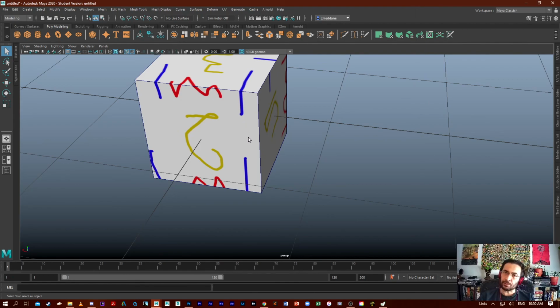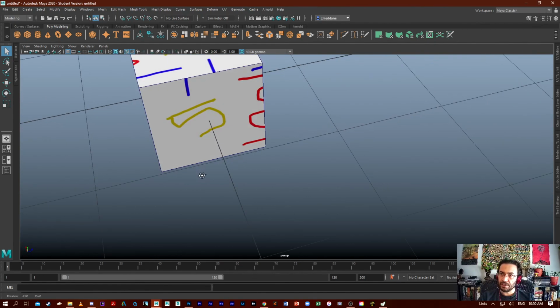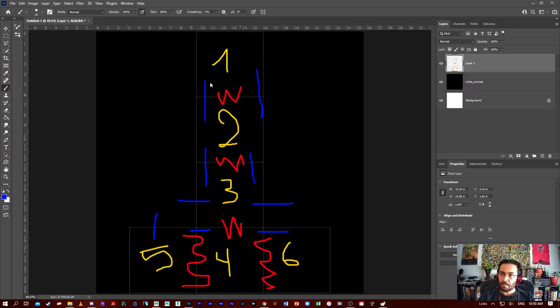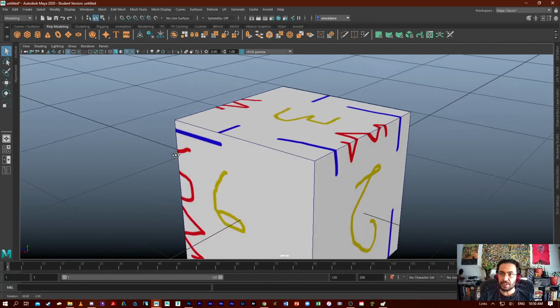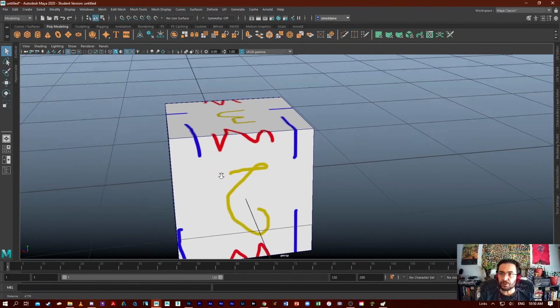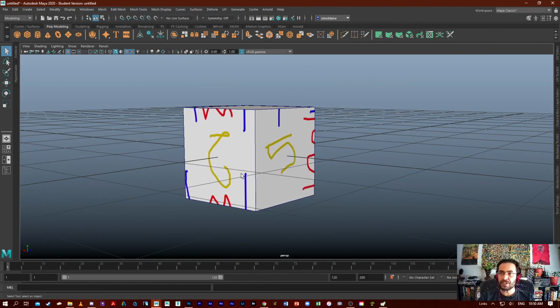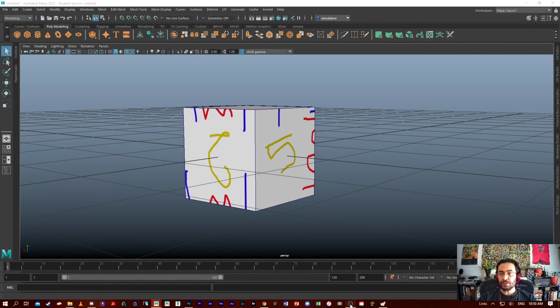But now the challenge with the seams is what I tested here for this edge, which is the cut with this one. So as long as those are not perfectly aligned, so there is a seam, you'll see that they're not going to get connected properly the same way as here. Now look at the opposite way. So the trick is to always think about how you are going to deal with the various seams around your object, because they will be visible and you don't want that.